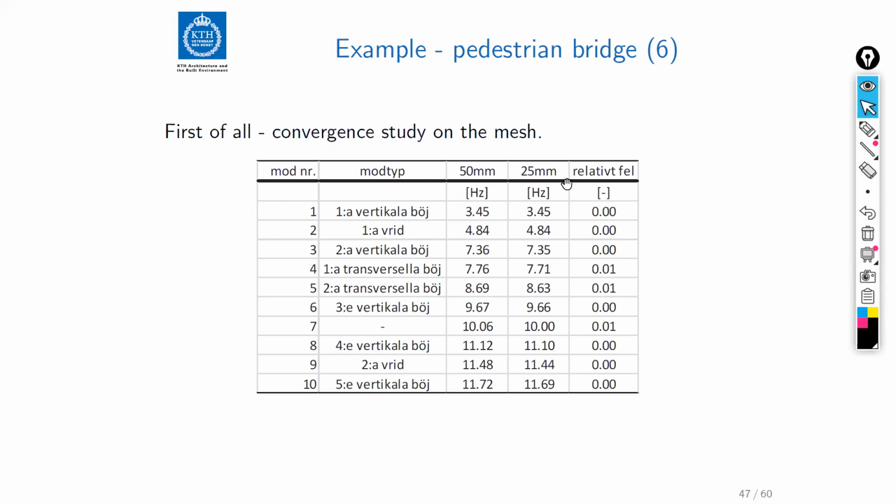First I did a convergence study on the mesh, and I've been doing this for some time, so I knew where to start, and this 50 millimeter mesh would be good. Then I ran one with 25 millimeters just to make sure.